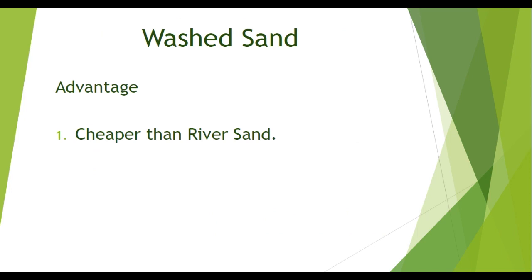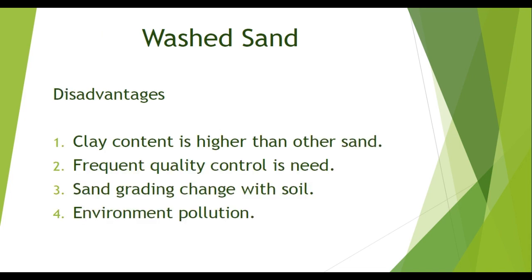But advantages are cheaper than the river sand. We can prepare it ourselves, and normally it's cheaper than the river sand. There are more disadvantages. First one, clay content is high. Normally we can't completely wash the soil, therefore clay content is there.